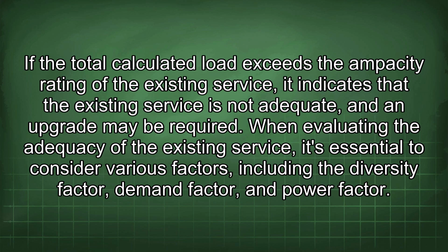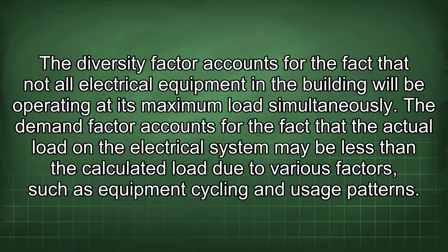When evaluating the adequacy of the existing service, it's essential to consider various factors, including the diversity factor, demand factor, and power factor. The diversity factor accounts for the fact that not all electrical equipment in the building will be operating at its maximum load simultaneously.